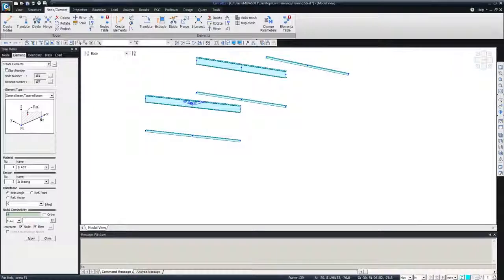So it means the software automatically considers the center point of each element. If I increase it to 3, for example, you see the 1/3 option is automatically recognized. And then you can also increase it for more convenience. For now, I just set it to 2, and I start creating these cross frames.